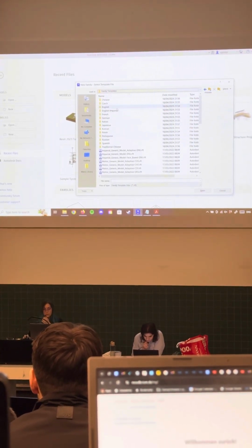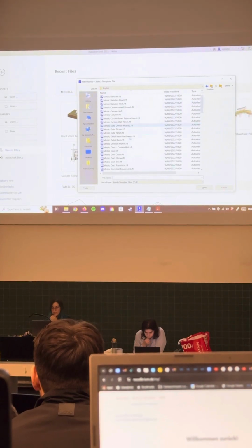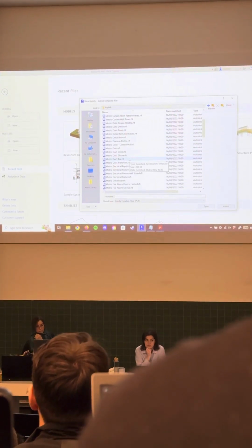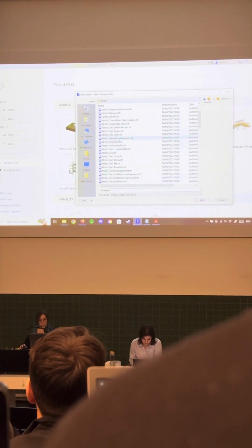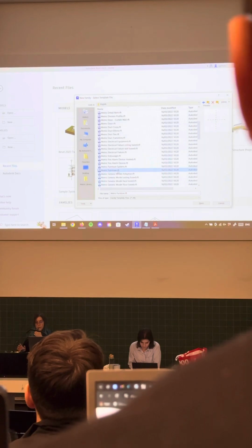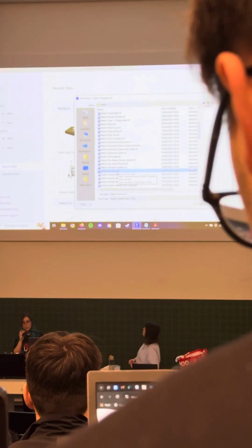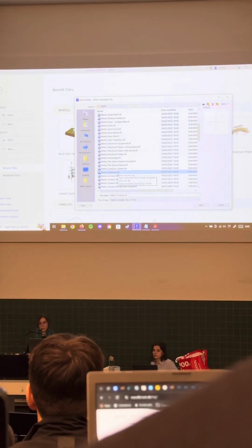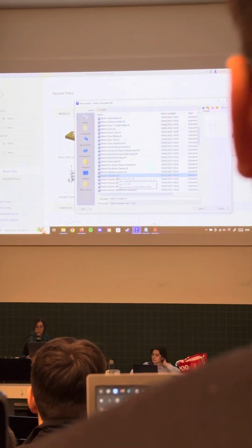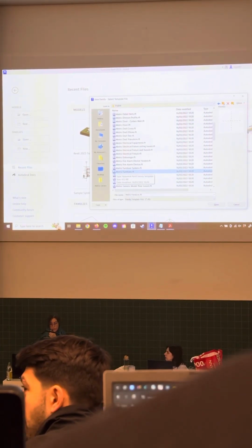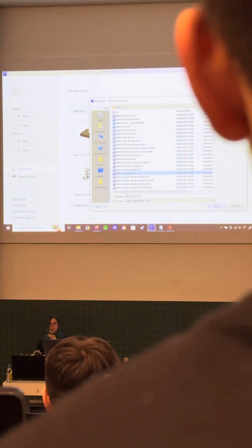As you see here, I'm going to go with the English one. And here we can choose the template to use as a base for creating, in our case, a furniture element. I recommend that we use, in our case, metric furniture, because this way the element that we will create will already have the property that it is like a furniture when we export it in the IFC. It will be classified as a furniture. So after we have found this metric furniture, we just click open.